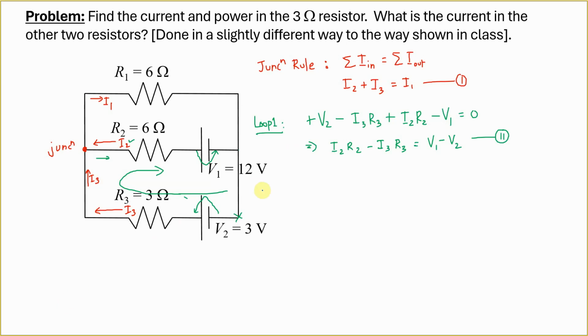Alright. So then let's go to loop 2. Loop 2 is the upper loop. Okay. So I start, let's say from here, I go around the loop, let's say in this direction, and I complete my loop just like I did for loop 1. Alright, so now this is my journey, the blue pen. So I start my journey here. I start walking again with a positive charge in my pocket, as always. You must have extra positive charges lying around in your bedroom so that you can always pick it up.